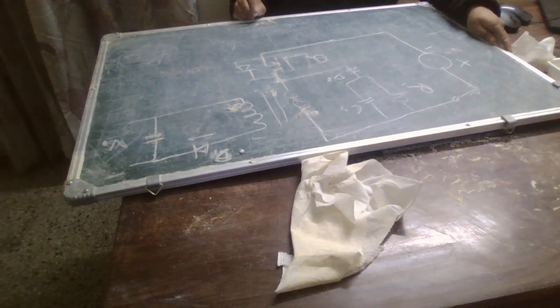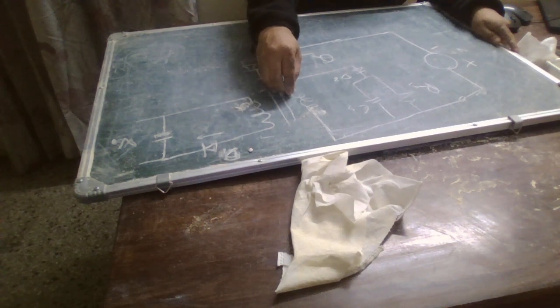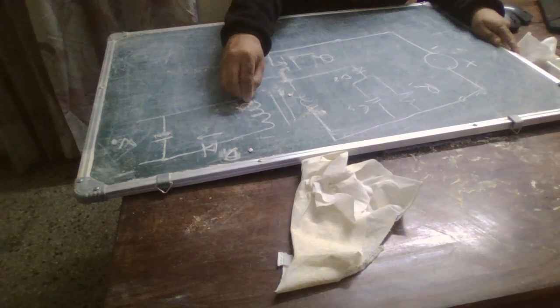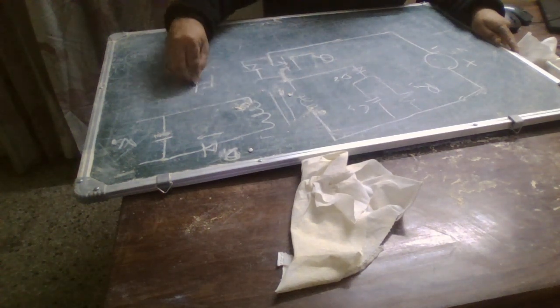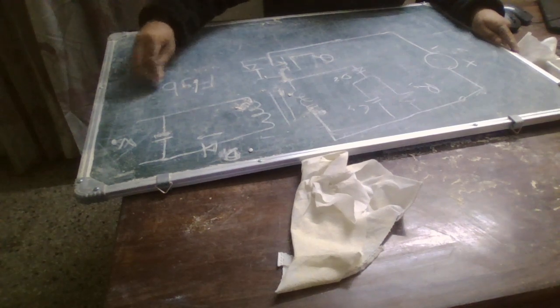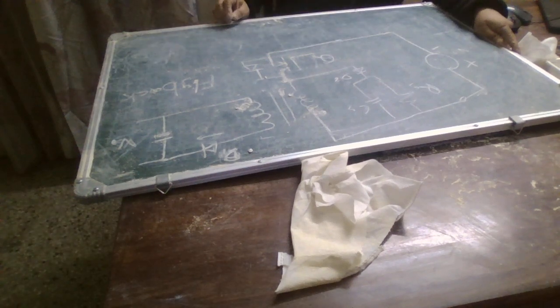Now the important thing is that the energy which is stored in the primary is transferred to the secondary, and this happens through the action called the flyback action. Because of this it is known as a flyback converter: the energy stored during the t on time, when the switch is closed and the transformer was behaving as an inductor, is transferred to the secondary through the flyback action.